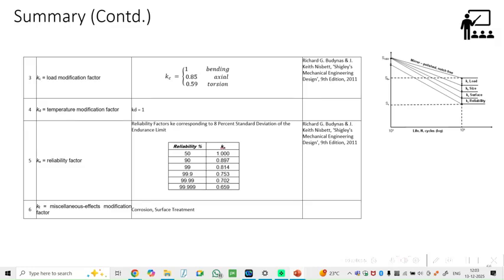They do chemical milling to reduce the thickness, because the sheet comes in a standard thickness, it may be 1.6 or 2 mm. But in the analysis, it shows the skin between two frames and two stringers. Usually the standard benchmark is around 500, I'm talking about single L. In the center fuselage it will be around 500, and stringer to stringer 180 mm. Towards the rear, frame distance will differ. So that's called skin pocket.